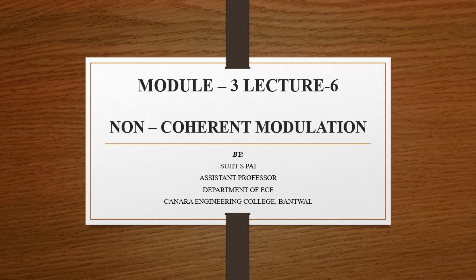Hello everyone. Today in this lecture we are going to deal with non-coherent modulation. In the earlier lectures, lecture 5, lecture 4, lecture 3 and lecture 2, we dealt with the coherent type of modulation. So what was coherent modulation? We had an additional reference signal which was used in the transmitter and also used in the receiver to nullify and to have a synchronized reference.